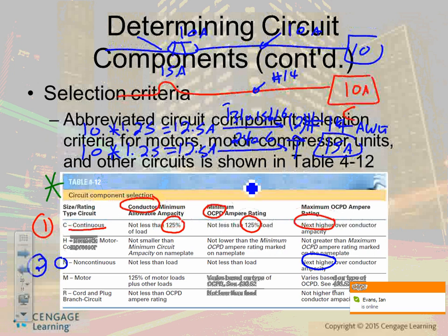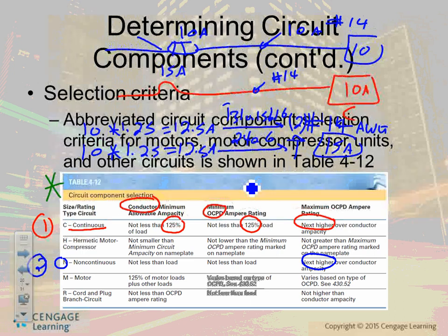Typically, we don't program this at 15 amp circuits. We don't. But that's how your system would be. And the conductor, we can't go lower than what? Number 14 anyway. Any comments, guys, about non-continuous, how you size it? Straightforward, no multiplication. Just go to the code and the two tables. Okay. These are the single most important thing, guys. Very, very important how to size them based on continuous, non-continuous.